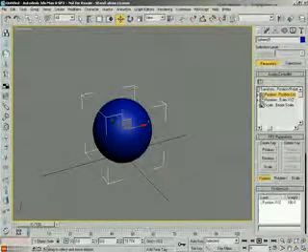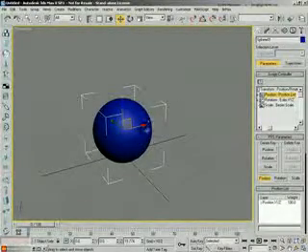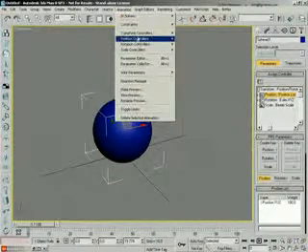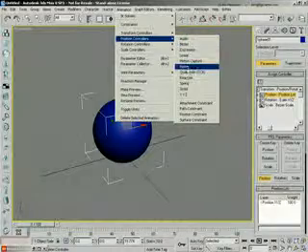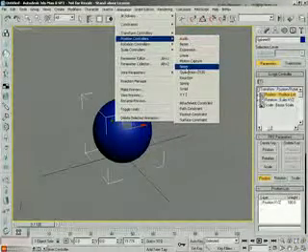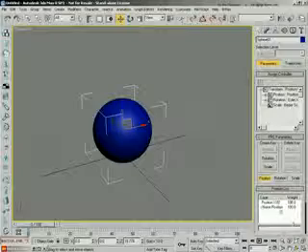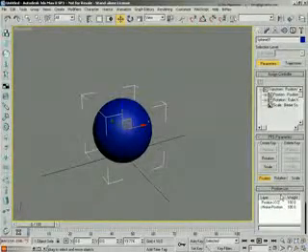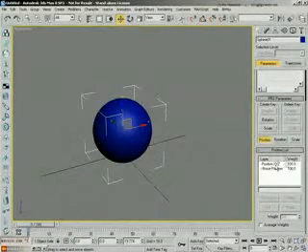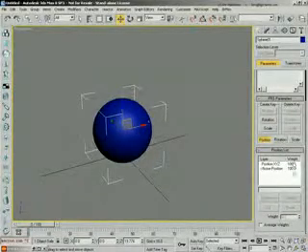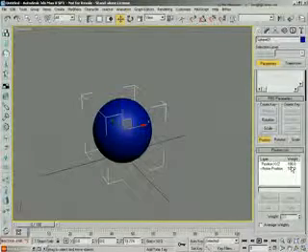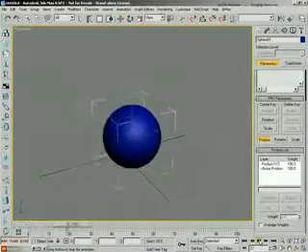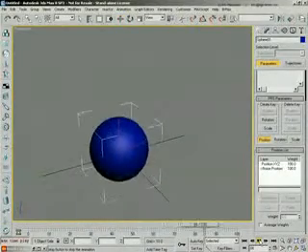using our move tool. So what we're going to do now is apply a noise controller to this. So if we go up to animation, position controllers, and then noise. When we do that, you'll notice that in our position list we now have a noise position assigned. Now if we look at the weight channel, which is directly to the right of it, you'll see that both are set to 100%. So if I play this back really quick, you can see it's jittering all over the place.